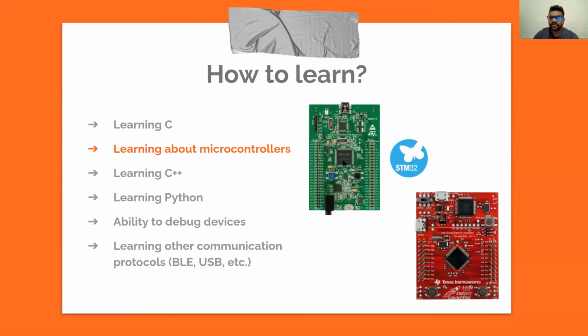And if you use a device like this and learn how to interface with I2C, SPI, and then different buttons, LEDs, and whatnot, you can connect anything here. This has even USB, so you can even develop USB applications on here, and you can just experiment with that and try to read the data sheet and learn what is there. Because if you learn how to read the data sheet, then you can learn about any microcontroller, any IC, any sensor. So it's very important that you read those data sheets.